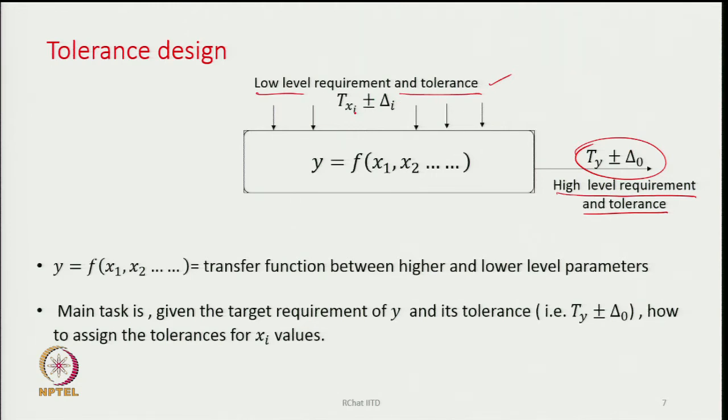Let us say as an example, if the higher level requirement is the strength of a fabric, then the lower level requirement will be strength of the individual yarns. Then another thing could be ends density and pick density. The third thing could be the type of weave, whether it is a plain weave or a satin weave or a twill weave. So, they become my low level requirements.